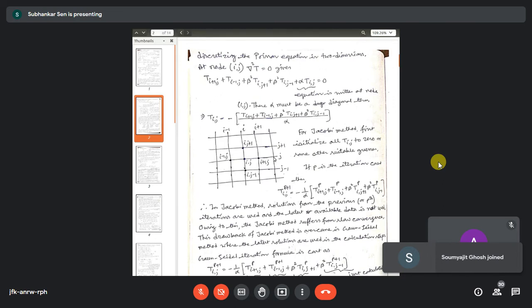So my point is precisely that whether you are solving the continuity equation or the x momentum equation or the energy equation, it does not matter. When you discretize it, you get a matrix, and then you simply solve this matrix. Okay, so here we are showing it for the Laplace equation. So it can be continuity equation for pressure, it can be x momentum equation for u velocity. In all cases, you get linear algebraic equations or linearized algebraic equations with maybe more number of coefficients.